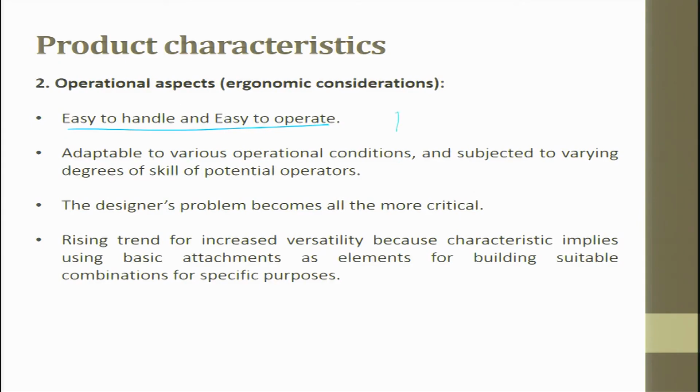Many a times the AC whatever we buy in India, they conk off when the temperature goes above 48 degrees or 47 degrees, because there is too much heat generation on the compressor side. The heat in the compressor could not be extracted, so it conks off. So, until the compressor is cooled, your AC will not work.